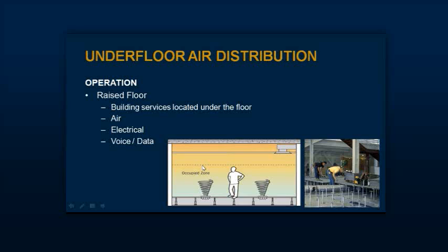And then you look at this other room in the Kaufman Center. I love wood. This is wow, okay? But we ended up putting displacement in here as well. Now this had a really stringent acoustical requirement, and one of the best ways to drop the acoustics down to even lower levels is to put in smaller volumes of air. So unfortunately this leads to more diffusers, as you can see underneath these seats on the right hand side of that little insert image. Well, the net effect is a very, very quiet, pleasing space. And again, no reason to air condition a space where we don't have occupants.